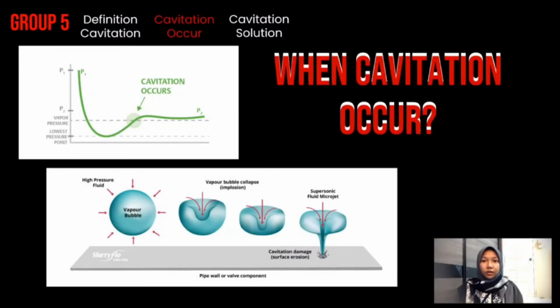When does cavitation occur? Cavitation may occur when a pressure drop occurs within a region of a fluid to a point below the vapor pressure of the fluid at the current temperature. At this point, the state change from liquid to gas occurs, creating a bubble. The pressure drop can be achieved in numerous ways, including the acceleration of the liquid as in a waterfall or propeller. After the cavities are created, the low pressure bubbles cannot sustain their form because they are surrounded by a higher pressure fluid, and they subsequently collapse.